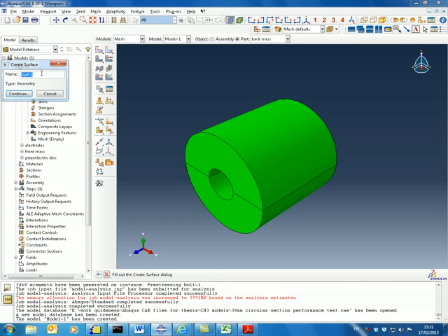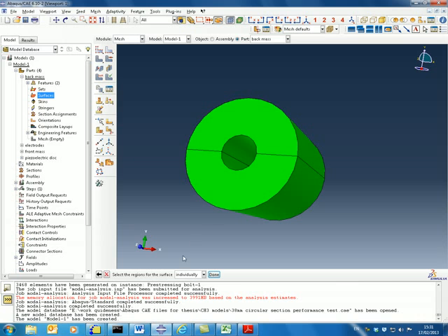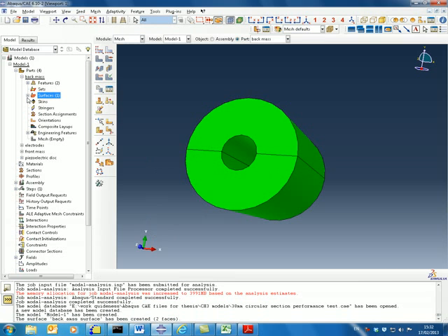So for the back mass, I'll create a back mass surface, and we can select each surface because it's being partitioned into two. We can select each part individually. So I select the first one, press shift and hold, and select the other. Or we could use by angle, so all the inner surface will be selected at once.